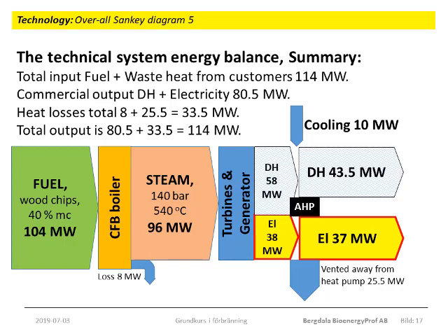Looking now at the heat balance for a system like this, it is important to understand that from a strict energy flow point of view, the commercial product called district cooling is not a plant output. To provide district cooling is to invite and allow the customers to dump their waste heat into the energy plant. So the district cooling is actually an energy input to the plant.